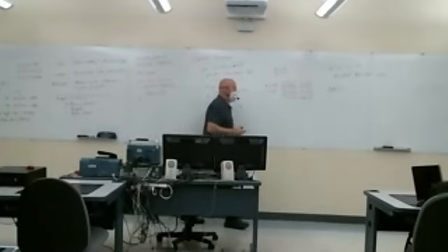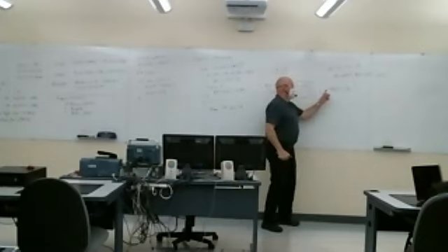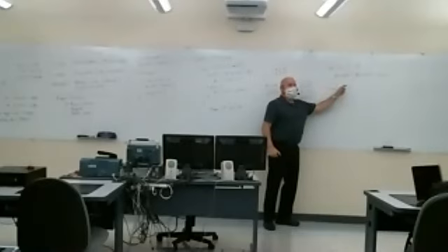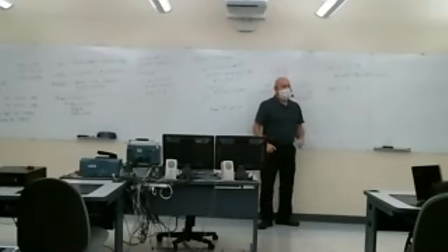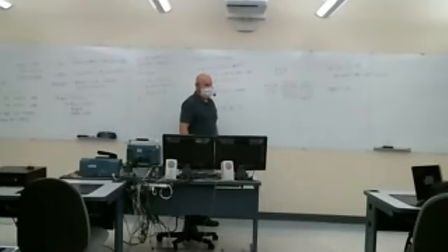It's always going to be A not. 0 exclusive or 1 is 1, 1 exclusive or 1 is 0. So A exclusive or 1 is always A bar, the inverse of A. So that's going to flip a bit.